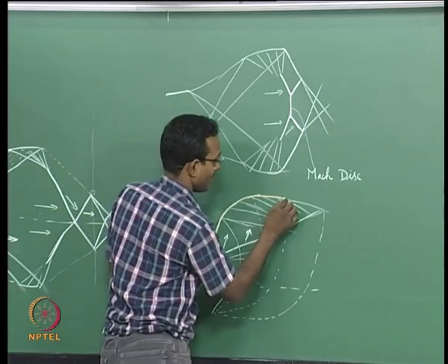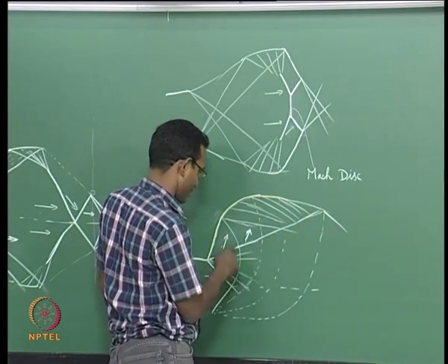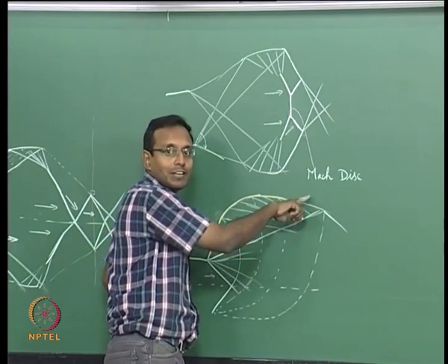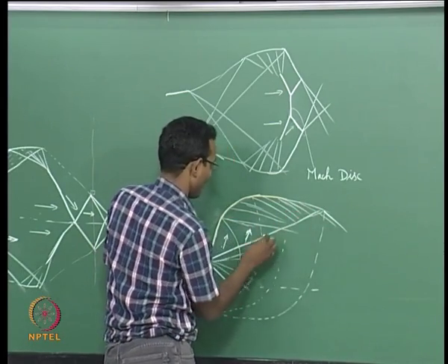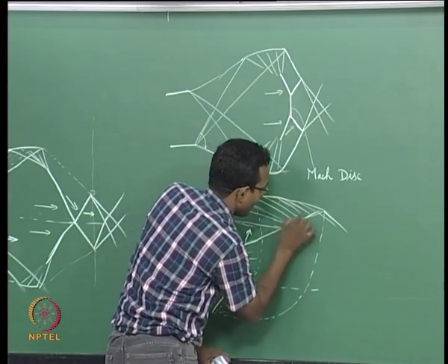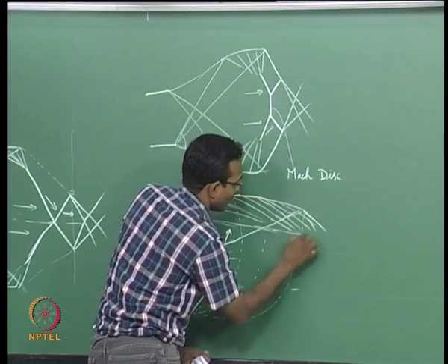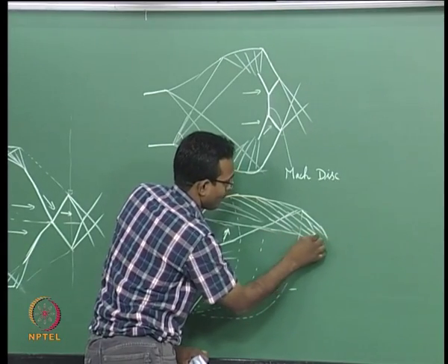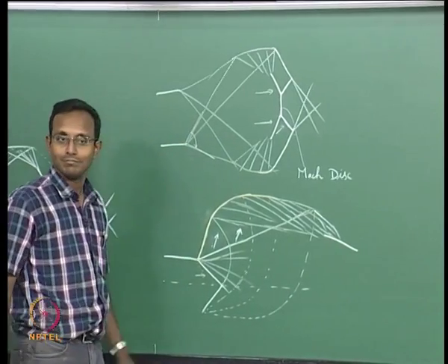All of them going and hitting, they are all going to start turning there. That will be a little stronger because two expansion waves go and hit, it will come back as a slightly stronger compression wave. A whole bunch of them coming together, they will all meet, compression waves you know, they come together and they are going to meet and form a shock at some crazy angle like this.